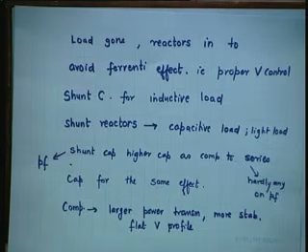Now, if the load is withdrawn or gone, then reactors are needed to avoid the Ferranti effect. So, that is where you need reactors. Do not think that you do not need reactors, that you need only capacitors. Sometimes the load is thrown off by accident. In a way, it is a fault.